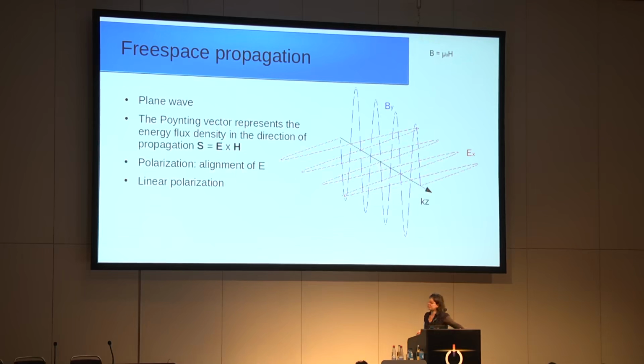A plane wave can be seen here, for example. So we have an E field and an orthogonal magnetic field. Plane waves are defined to have a constant frequency. The wave fronts are parallel planes of constant peak-to-peak amplitude, and all normal to the phase velocity vector.